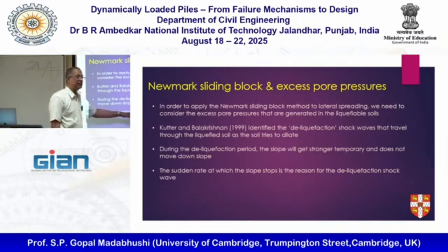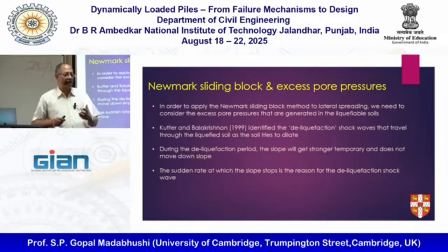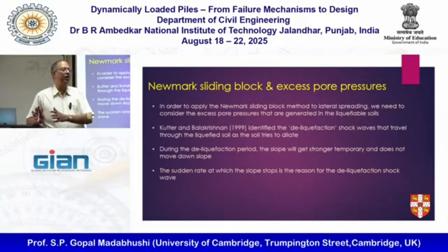And this also explains why in the centrifuge tests and experiments we do, we see the slope suddenly stops and then moves and stops and moves as well. And it's all linked to pore water pressure. In the whole of soil mechanics, as I said yesterday, there is only one big thing you need to understand. The soil behavior is linked not only to the stress state it is in, but it is also dependent on its tendency to have volume changes.